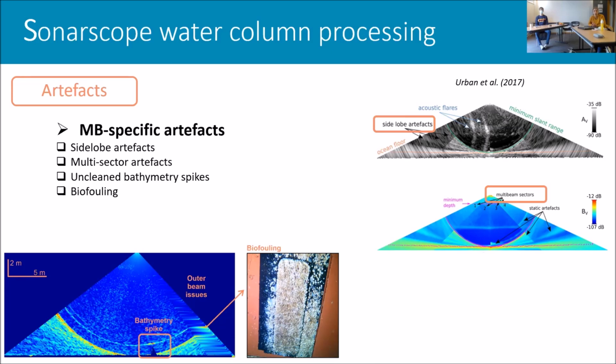And then finally, the biofouling we also encountered, sadly, because it can seriously deteriorate the data quality and you can have issues with your outer beams like you see here. So this can be avoided by a more regular check of the transducers.